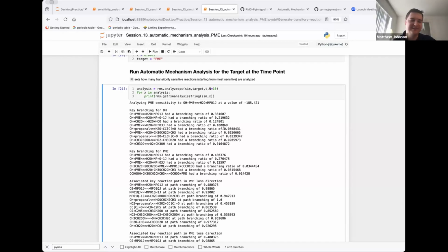But if you know your flow rate, you can just say, since we're keeping constant temperature and pressure, we're going to simulate in a batch reactor that has the same temperature and pressure. And that will give you the exact same simulation as that. Does that make sense? So for the plug flow, there's an equivalent reactor set.